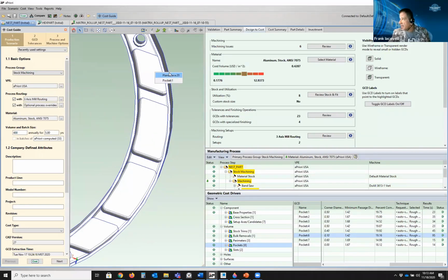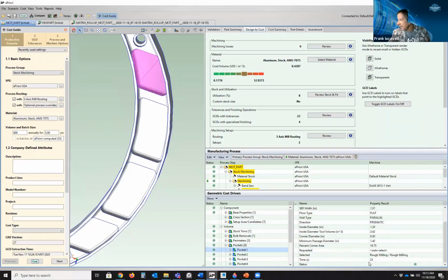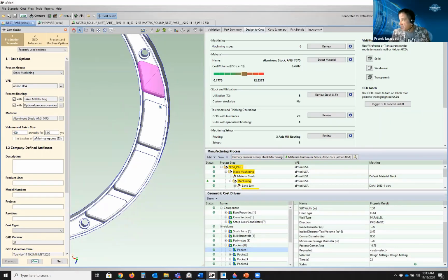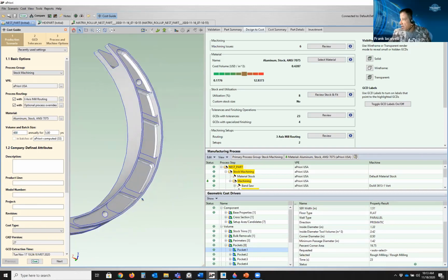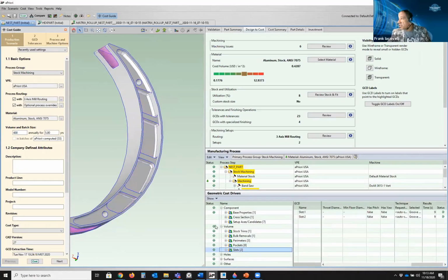Versus this pocket on the same side only takes 23 seconds to make. Again, it has fatter radiuses. It's a better designed pocket unless this is for some specific reason other than the engineer wanted to put a small round there. Also slots here.